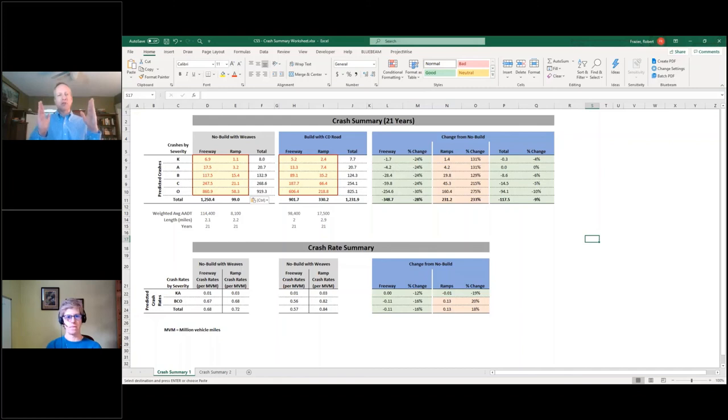Often for safety, we'll have a little discussion with the operations folks and say, well, 20, they want those 2 years, and so maybe we'll do those and match them. And then maybe for the 20-year analysis, we'll say, can we do the first entire year that it's open to traffic? And so we'll slide that back to 2026 and 2045. And then we've got a 20-year period, or just use 21. There's more than one way to do it, but I just want you to be aware, that's why that number is strange.